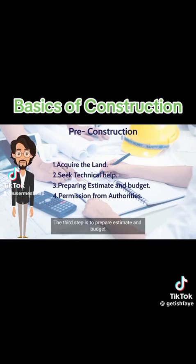The third step is to prepare an estimate and budget. Building construction involves a huge amount of material and budget. After planning and structural detailing are completed, these details are transferred to the building estimator. The building estimator will estimate the material quantity of different items of work, and prepare an abstract sheet that shows the cost of building construction.